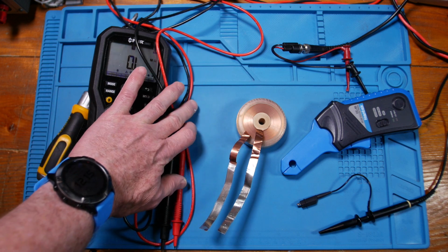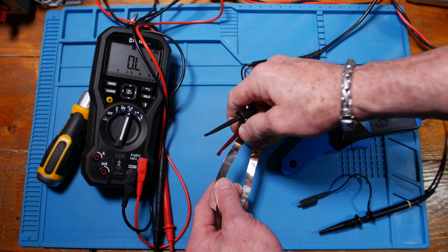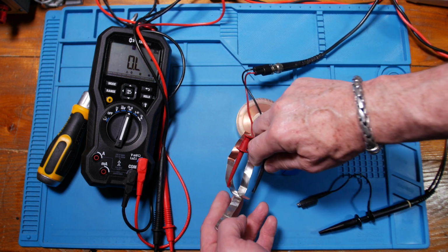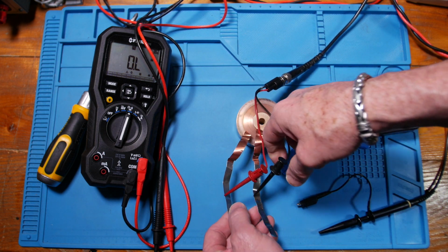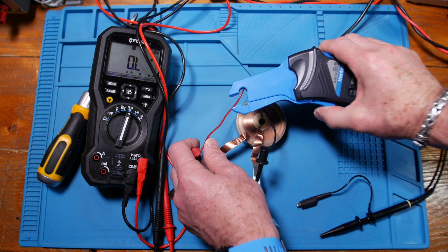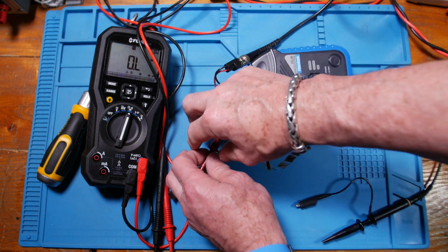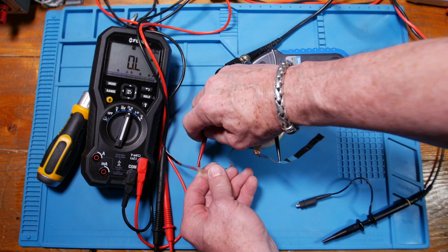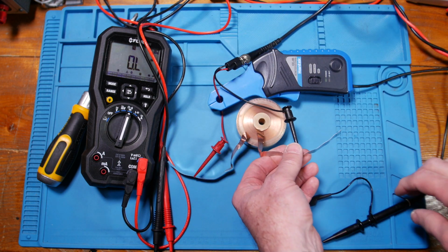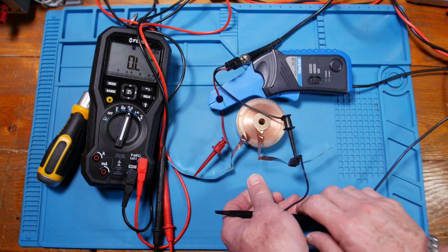Okay, so now let's measure. Okay, so we're done with this guy for now. Just move that aside. Let's put the generator on. We're going to put a frequency right across the coil and make sure we don't touch the leads. Now this current probe, we're going to read the current, and so the current wants to go down into it like this. Okay, there we go. And then we'll put the voltage probe here, right across the coil.